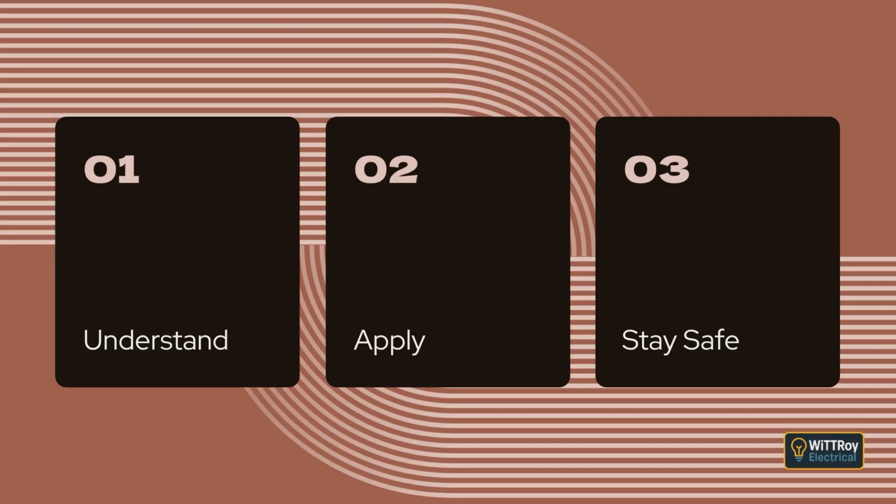Clause 3.9.4 Protection against mechanical damage. This clause explains where wiring is likely to be exposed to mechanical damage and must therefore be protected. Clause 3.9.4.1 General. Where it is reasonable to expect mechanical damage, the wiring system must be protected in accordance with Clause 3.3.2.6 and the detailed requirements that follow.